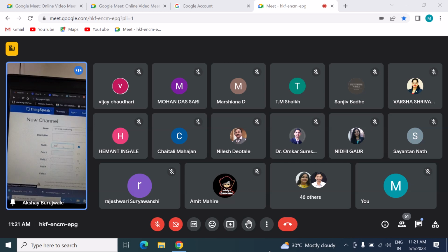Once you log in to ThingSpeak, you can go to Channels, New Channel, and create a channel with some name and the number of fields you need. Go down and save the channel. So the channel is created for IoT temp monitoring, and here are some settings like private view, public view, channel settings, sharing, and API keys. Here we have created one chart field, visible for the temperature.